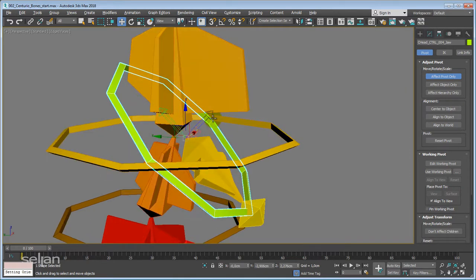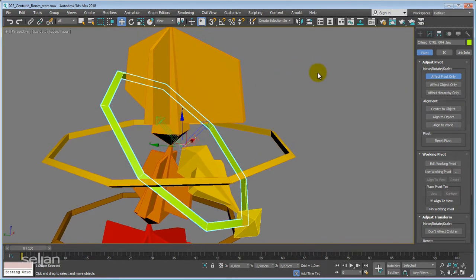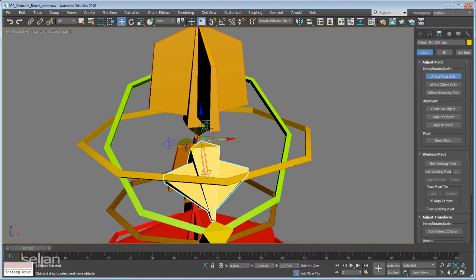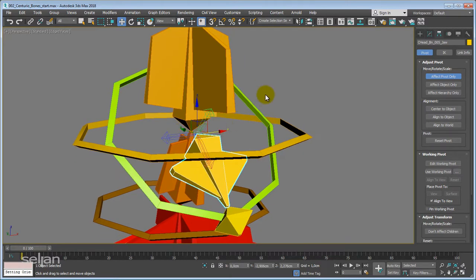The blue one is pointing in this direction. But now I will select the bone, and as you see, the bone's z-axis is oriented this way. When you create this constraint between the bone and the controller, this constraint will match the z-axis, the x, and the y-axis in both items. This is the reason why the bone is flipping.